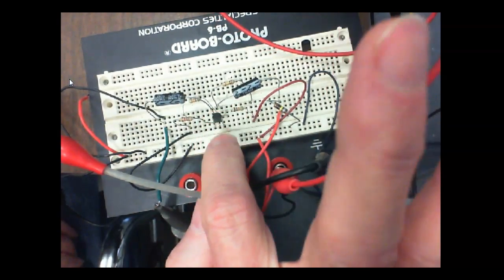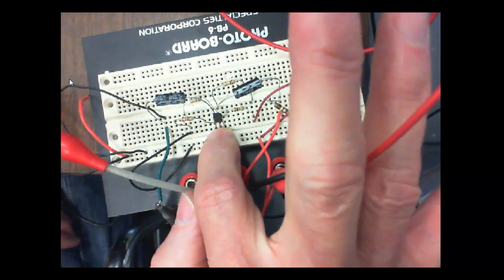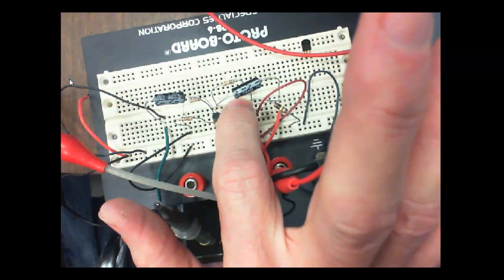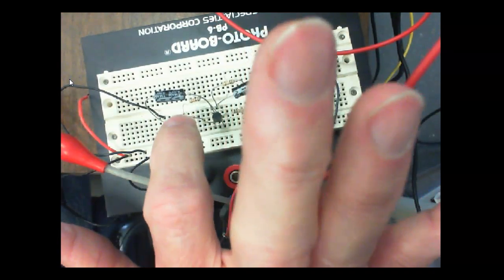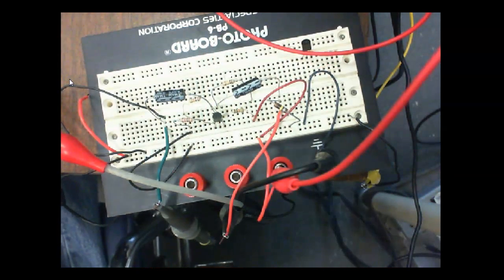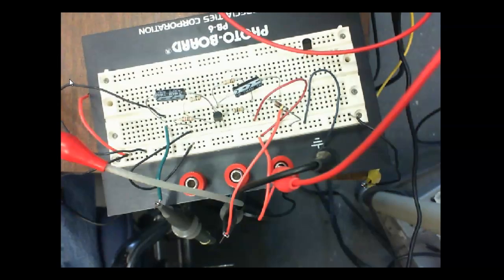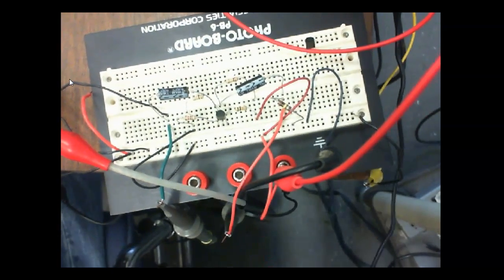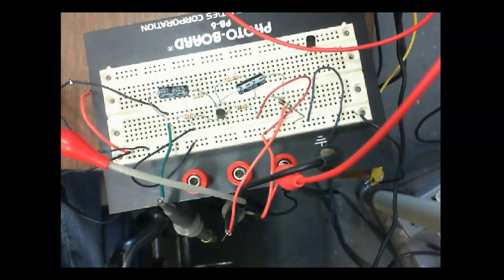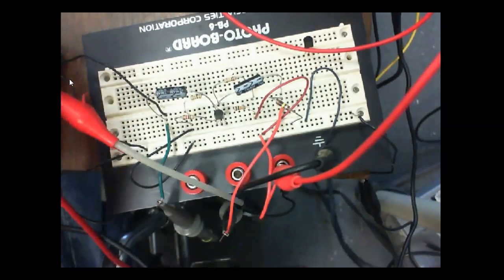So here's the 10K. By the way, the emitter is on the left and the collector is on the right. Well, this is one of the ones that y'all figured out. So I've got a brown, black, orange, which is a 10K. I've got it connected to the collector. Here's my emitter resistor. That's my 1K right there. I'm going to take my meter. And it's active. It's got an AC signal coming into it that I showed y'all. And normally what we do is we make our measurements to circuit common. That way you're only probing with one lead. So that's why when we calculate these, we try to calculate them relative to circuit common.